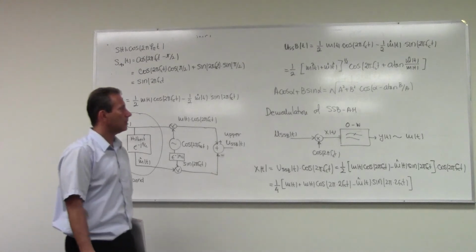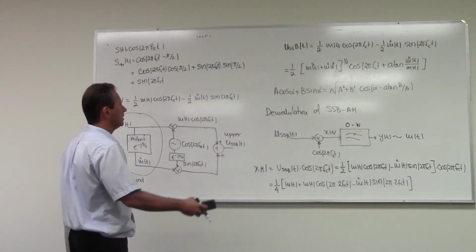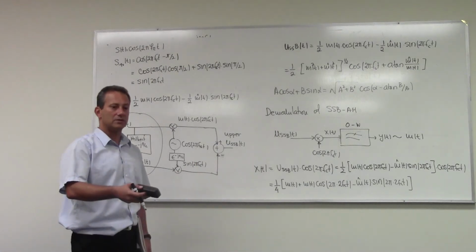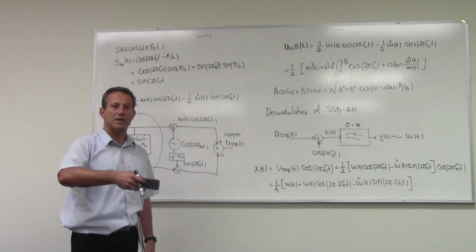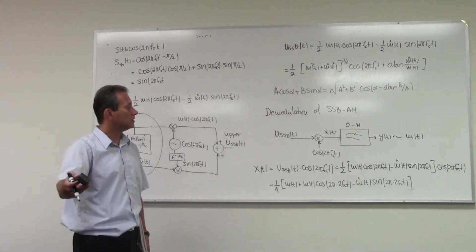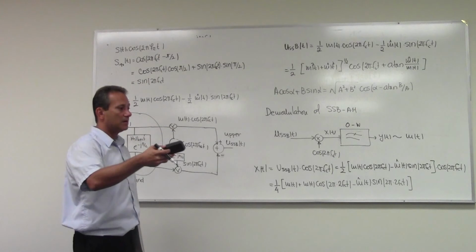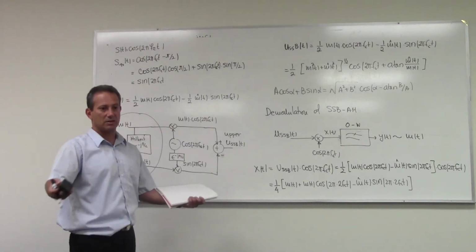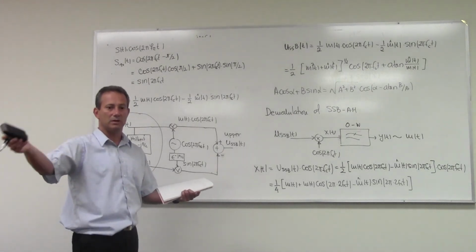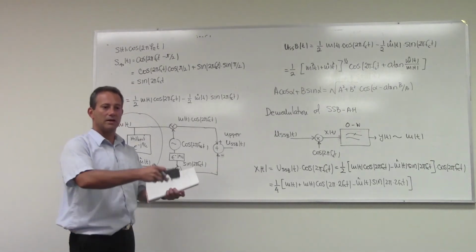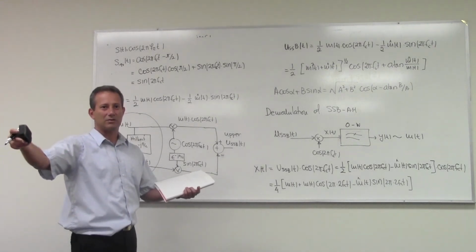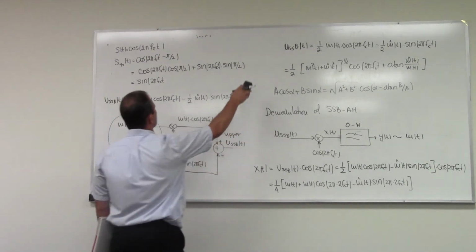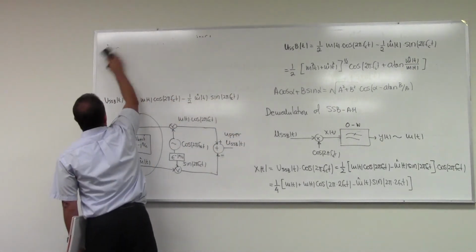Let me talk a little bit more about frequency division multiplexing, because now we have all of these three modulation schemes. Each one of them gives us the flexibility to translate the spectrum from baseband to whatever carrier frequency we desire. The double sideband modulation schemes need 2W, single sideband needs W, but nevertheless, the idea is the same. If I'm able to put it in a frequency domain wherever I want, why can't I stack them up one next to the other and then use the same line to connect the transmitter and the receiver? So let's talk about the basics of FDMA.